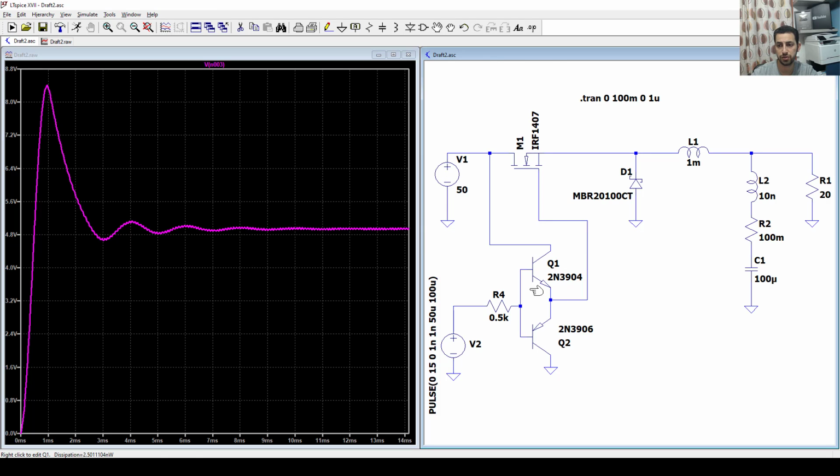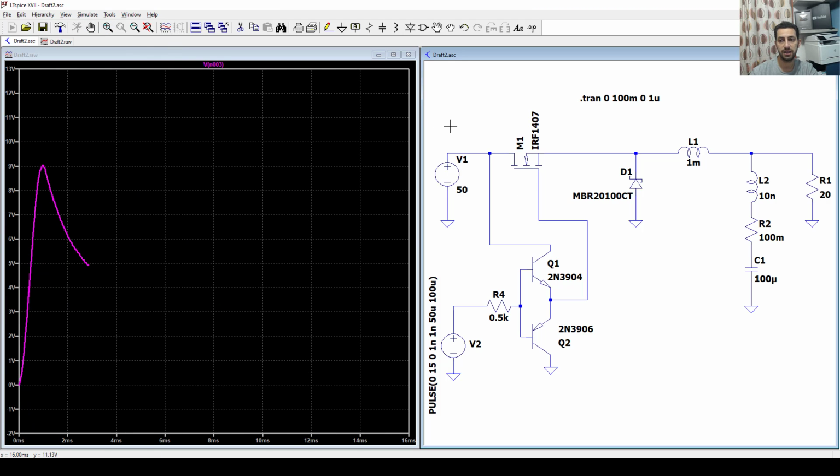We have the first transistor here, which brings the current from the top and goes to the gate to charge it and turn it on. That turns on when the PWM turns on or B1. So when the PWM is 0, that turns on this transistor, and that brings all the charge to ground and we turn it off. Okay, so let's now test this one and see if the output voltage will be alright and if the switching as well is right.